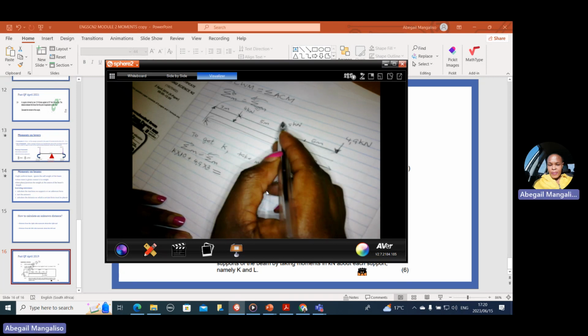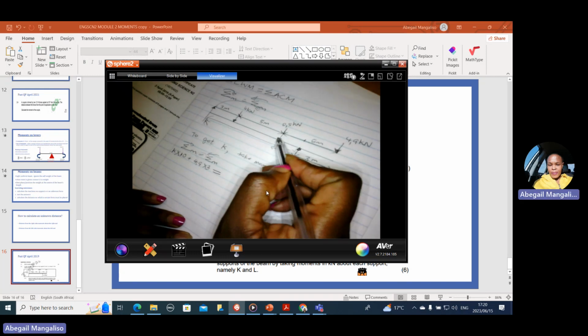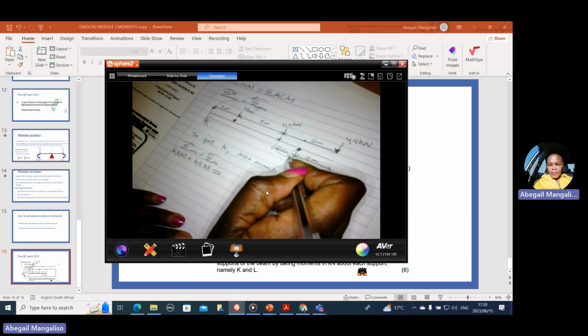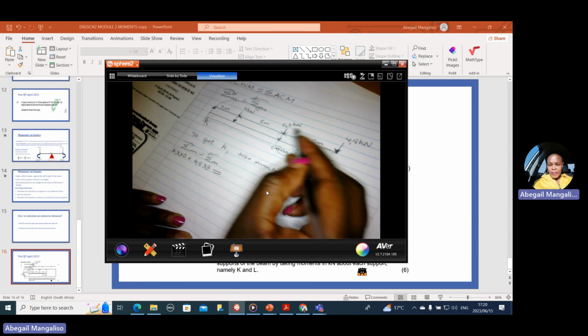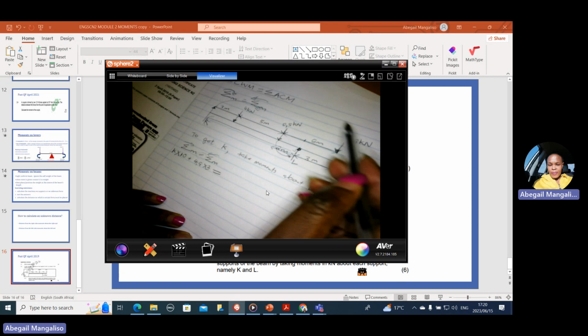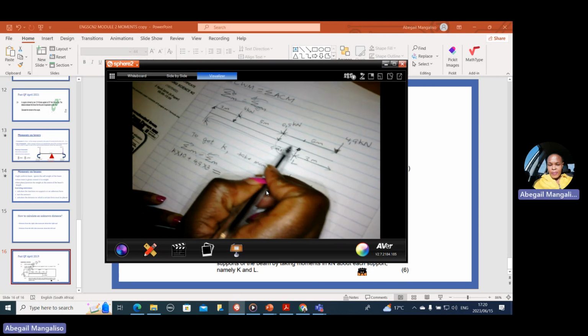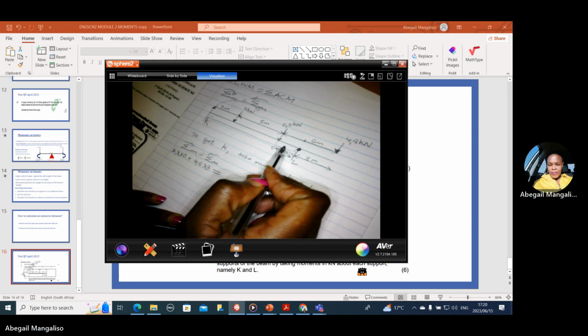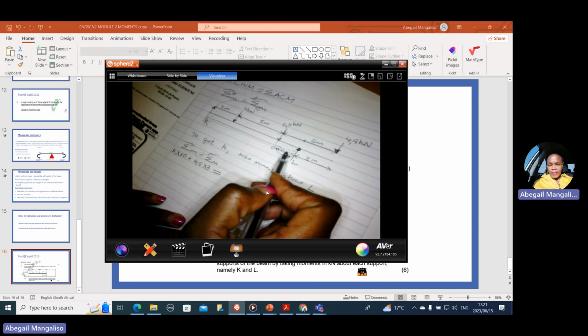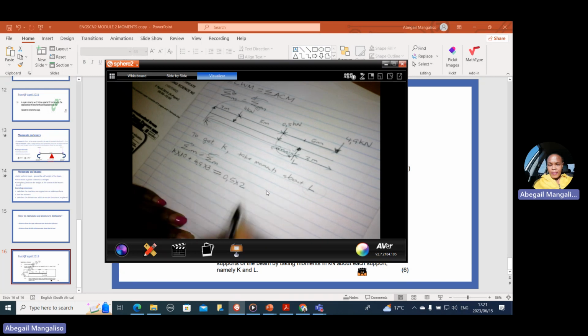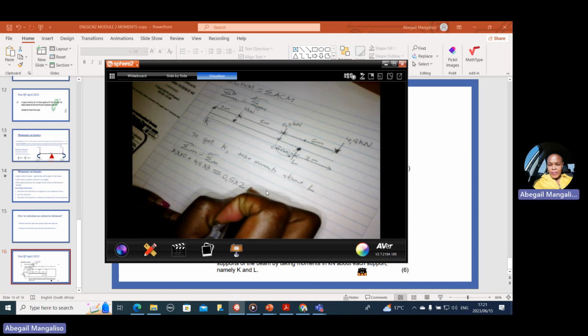Now look at this 0.5. 0.5 is downwards. So if we turn or push its arrow towards this point, 0.5 is producing an anti-clockwise effect. It is conveying energy to the same point for a distance of 2 meters. So it will be 0.5 multiplied by 2. This is the moment, force and distance. This will be plus.